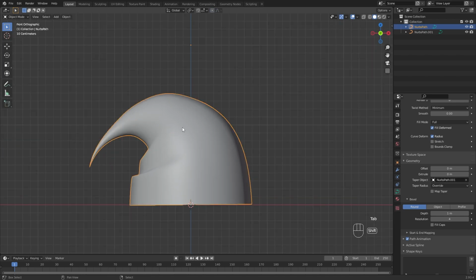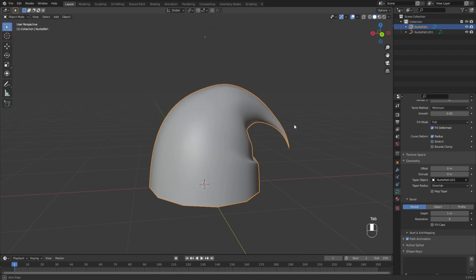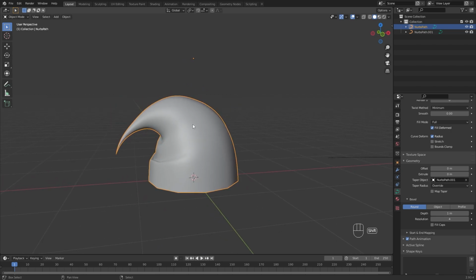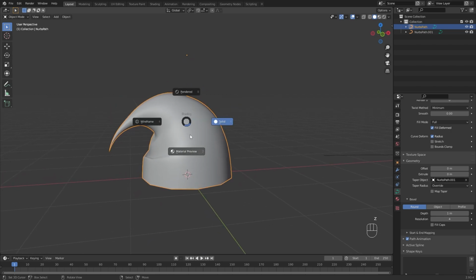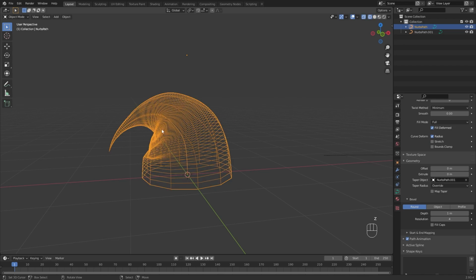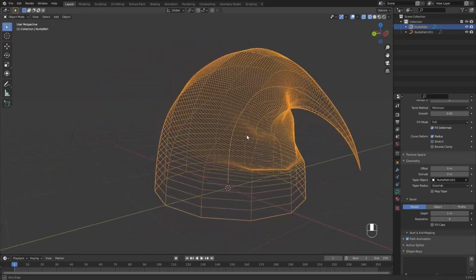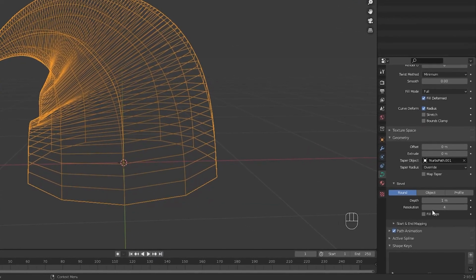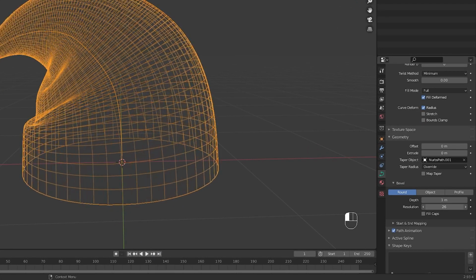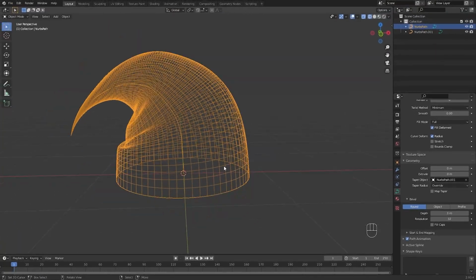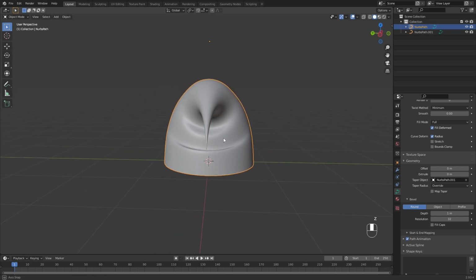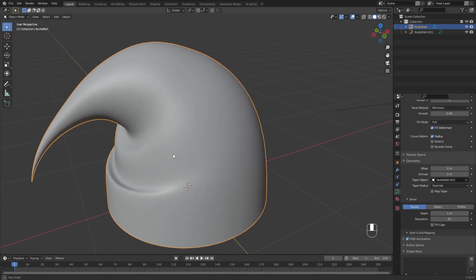After setting the shape here, let us now set the bevel resolution of this shape. Using the wireframe view, you can see exactly what this shape looks like. You can see that the faces of this mesh are not subdivided correctly. So, enter 32 for the bevel resolution value here. Okay, now the problem here is fixed. We have now finished creating the shape of the fabric part of Santa's hat.